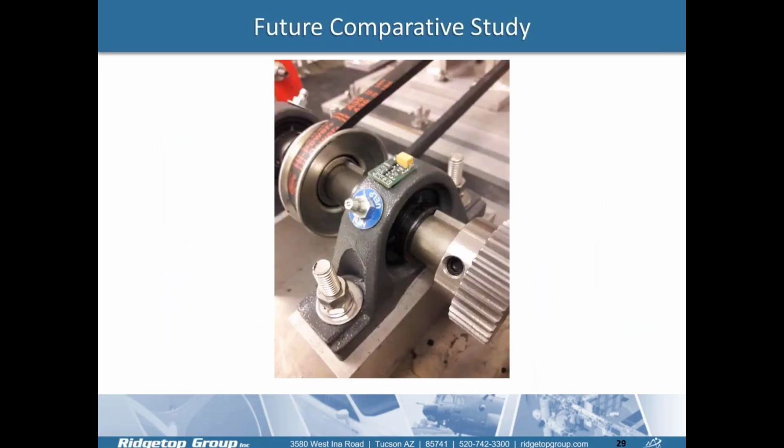But so far we mounted the accelerometer only on the shaft. So the next step, something left to do, is to mount the same accelerometer, the same RotoSense that I used for the signal analysis of the shaft, on the bearing, and compare the signal captured here with the other 2 signals that we collected from the shaft.